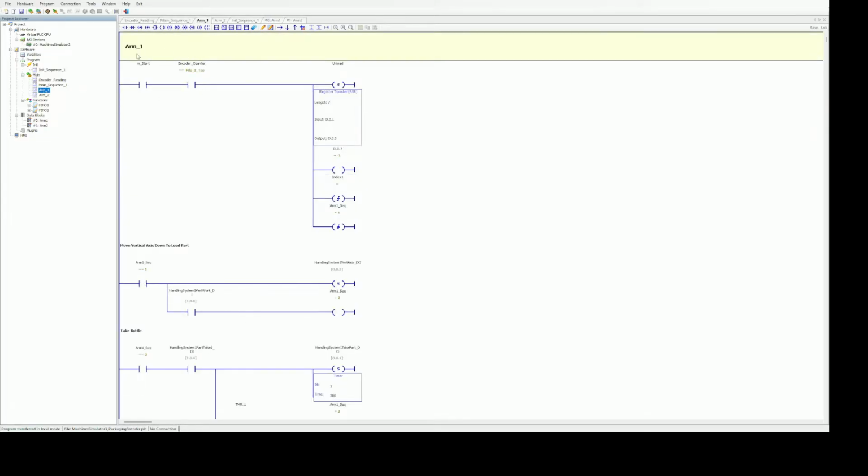The following sequence, ARM1, controls whether a bottle of the blue type is present in the output zone to be removed by ARM1. To do this, the first position of the stack for the type of blue piece is controlled. If the value of the encoder is the one that had the blue bottle in the input station plus the offset that indicates that the bottle has already reached its destination, then the following actions are done.